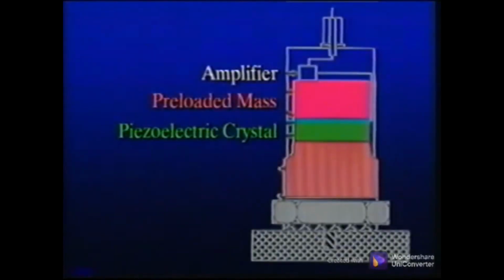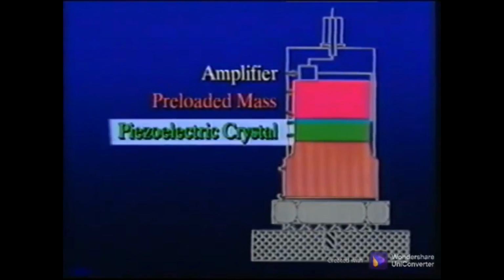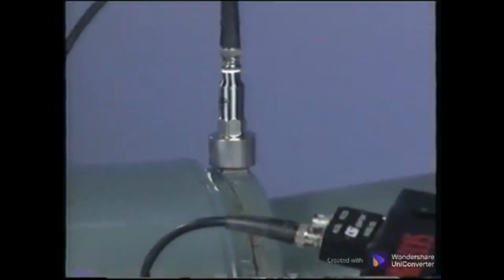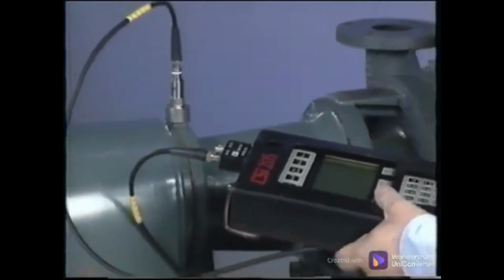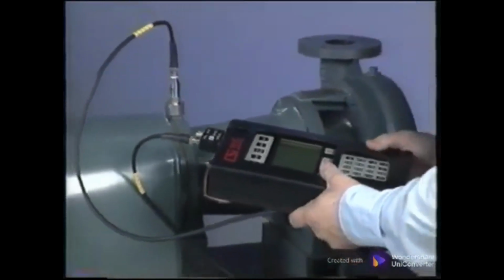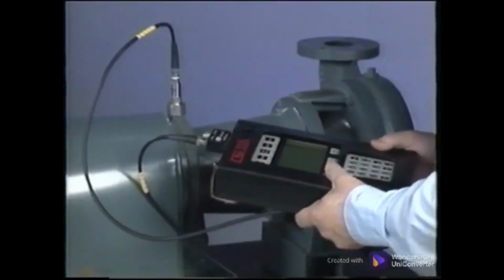Inside these accelerometers is a piezoelectric crystal. This means the crystal is under pressure, and when an electric current is applied, the output voltage changes with a change in pressure. The change in pressure is produced by the vibration of a machine impacting the sensor. The analyzer reads this voltage output and stores it as your data.